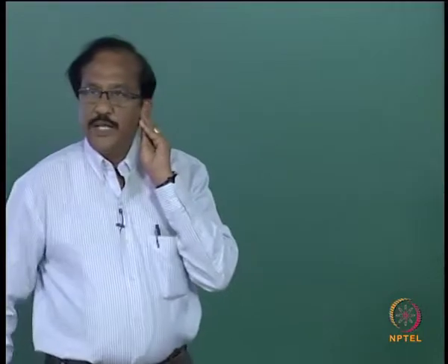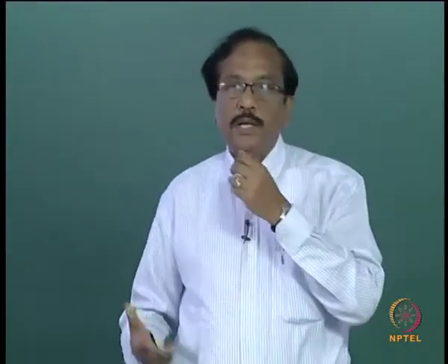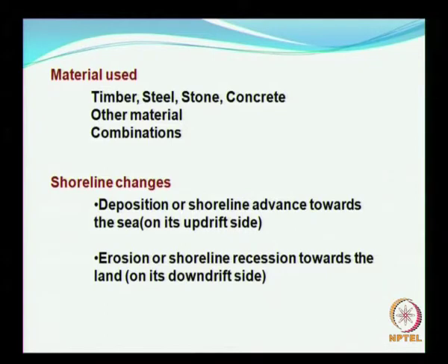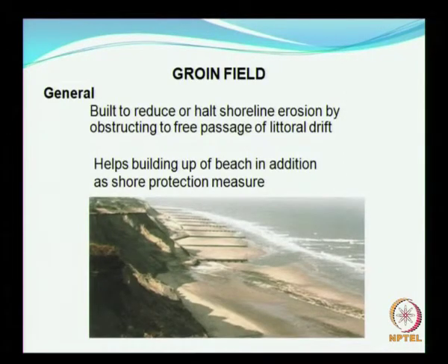Materials used: you can either use timber, people have used timber, steel, stone, concrete, sometimes there are some other materials. Under other materials I can also suggest the geosynthetic tubes, which we will see later, or gabions. And as far as shoreline changes are concerned, we have already seen enough about the shoreline changes, and we will move on to the next slide. This is a picture showing how effective the shoreline or the beach formation is when you have a groin field.